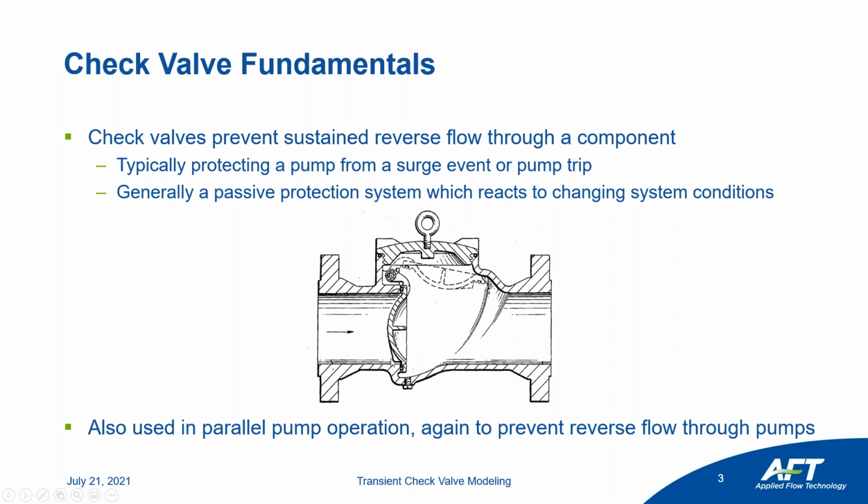And now all of a sudden, when this valve fully closes, we're bringing all of that flow to a stop. So in the same way, thinking about a traditional valve closure, if you close it very rapidly and flow comes to an abrupt stop, that's going to cause a high pressure event. In this case, it's specific to how a check valve is constructed, and we call that high pressure response check valve slam.